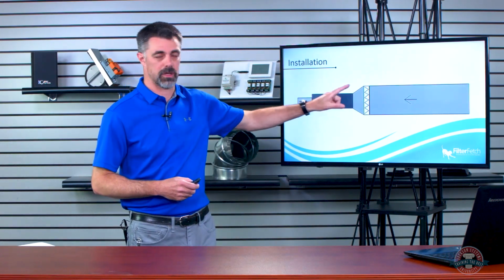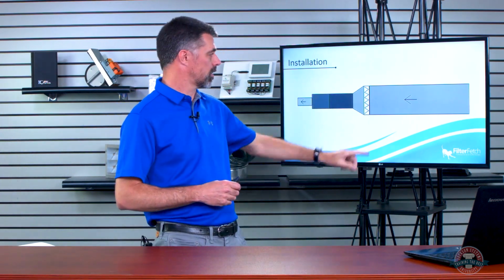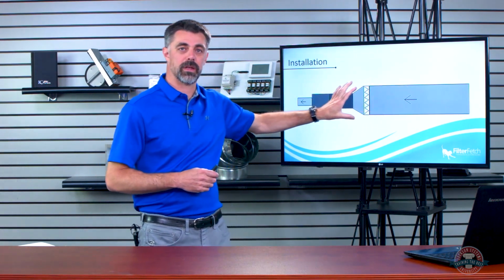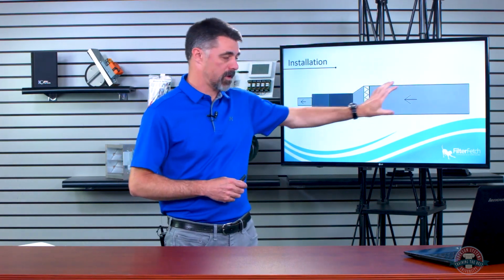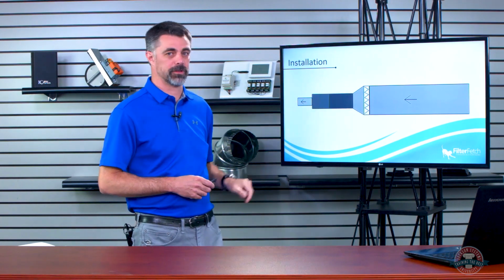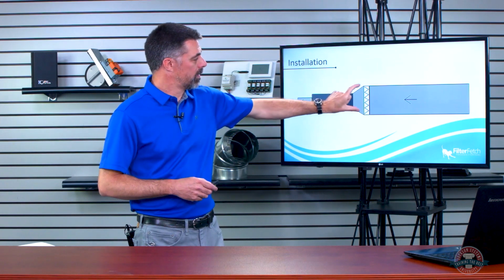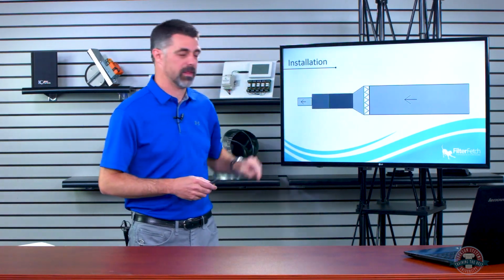So we'd make a transition here. Metal, duct board, however you need to do it. We need to make sure that the filter surface area is accessible to the airflow. We really need a nice long plenum coming in that's fairly straight before that, if you have the space. If you don't, we'll look at some options for that. We want that air coming as straight as possible into that filter. Next slides, we're going to talk about the straight air coming in. And then we want a nice transition down to the inlet of the equipment so that we can bring that air down into that inlet.